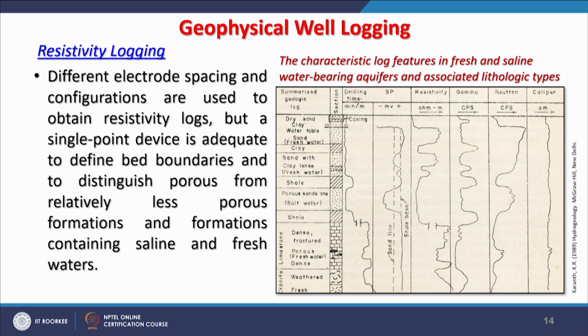If we see a resistivity log here along with the litholog, then we find that we have now encountered the water table here. Resistivity shows a completely different signature as soon as we encounter the water. Then as clay formation comes, it goes down and then comes up again, and likewise it keeps changing. So, the resistivity log shows a very good match with the litholog.